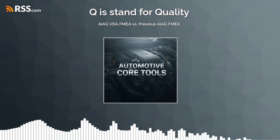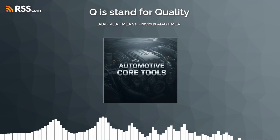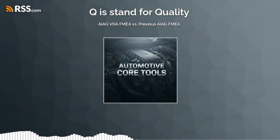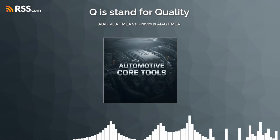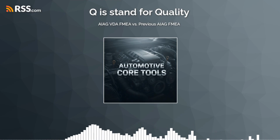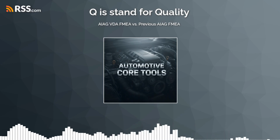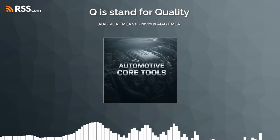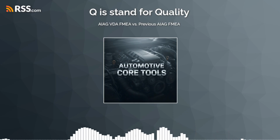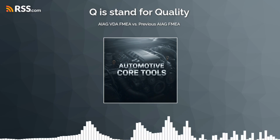That feels like a major mindset change, really putting severity right up front. What about how the pieces of the system itself are broken down and analyzed? Is there a difference there? Yes, definitely. The AIAG-VDA method significantly ramps up the requirement for a systematic definition of the relationships between structure, function, and failure. Okay, structure, function, failure. Right. It's not enough just to list potential failures anymore. You need to clearly define what the system is, what its parts are supposed to do, that's the function, and then how those parts or the overall system might fail to perform those functions.